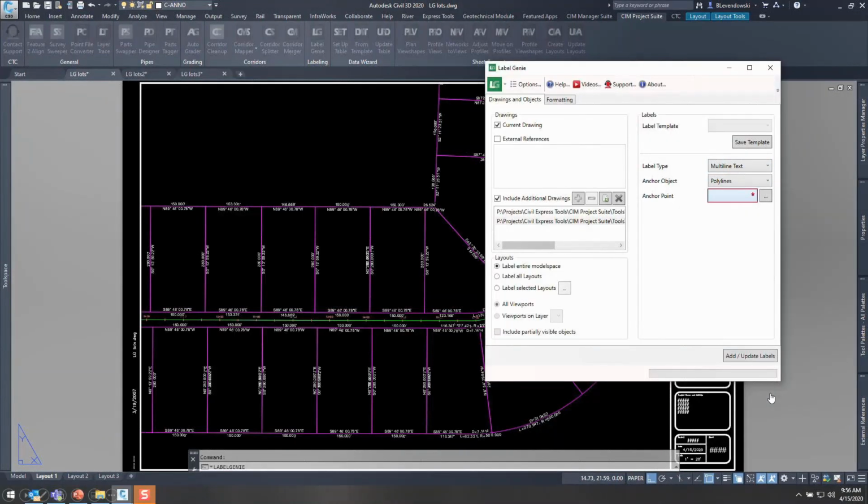Let's take something as simple as M-text, right? Civil 3D labels are decent. They're really nice. They read the objects, but we're just putting M-text out there for a lot of things. And it's a manual process. Even if you insert an AutoCAD field in an M-text, you've got to do it one by one.